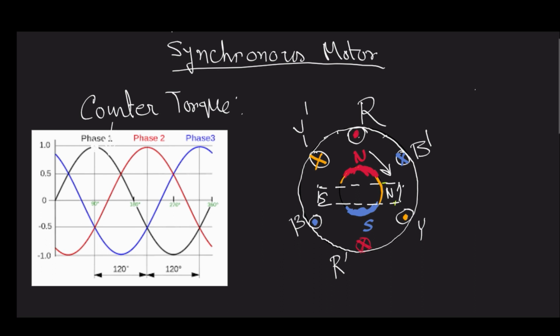We have already proved that this rotating magnet will be 3/2 F_M. Now see the polarity. Here this one is creating N, and it is trying to rotate in this direction. So this N will always try to repel the rotor in the reverse direction. That is the genesis of our counter torque.